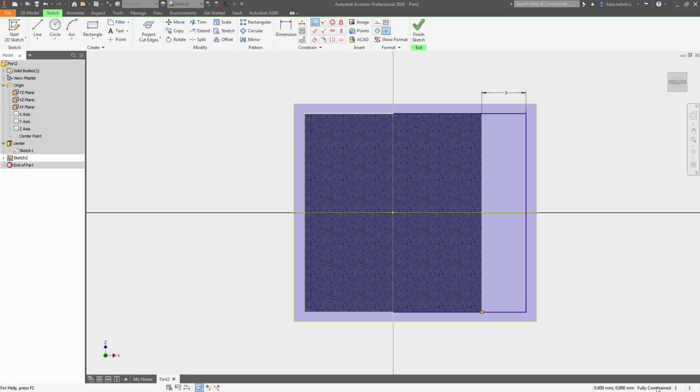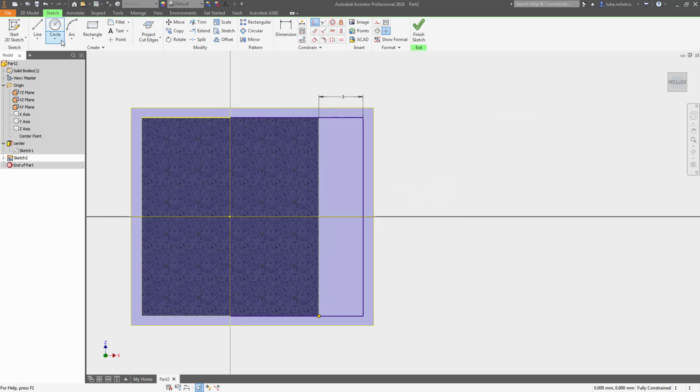It's kind of a helper there so that you can make sure you're creating fully defined sketches, because you always want to fully define your sketch 99.99% of the time. We'll continue sketching here. So I'm going to go to my line command, hit Escape L. Got out of the dimension command or the constraint. I'm going to basically snap to that point.